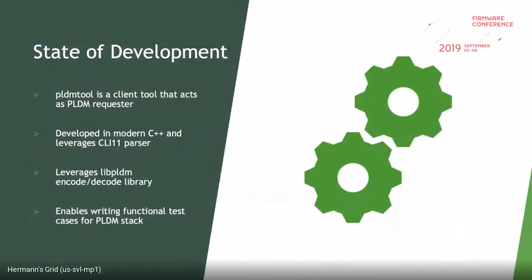So, the state of development right now on the tooling front. I have used IPMI tool for quite a few years, so the immediate name that came to my mind was PLDM tool. We were implementing the PLDM specification, so we started off with the PLDM tool, which acts as a requester and runs on the OpenBMC. Unlike IPMI tool, which typically runs outside the BMC and targets it via network, the PLDM tool runs on the OpenBMC as a PLDM requester.